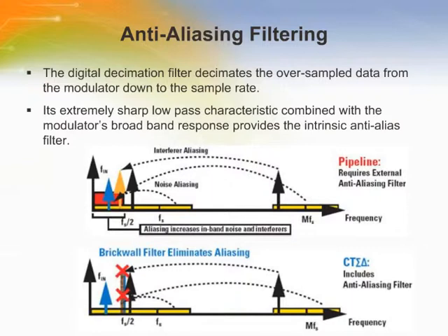The CT sigma delta analog to digital converter architecture eliminates the need for stringent input filtering because of its inherent anti-aliasing filter. In the ADC 12EU050, many of the performance characteristics of the anti-aliasing filter, AAF, are set in the digital domain, allowing for a very high level of passband flatness and steep roll-off.